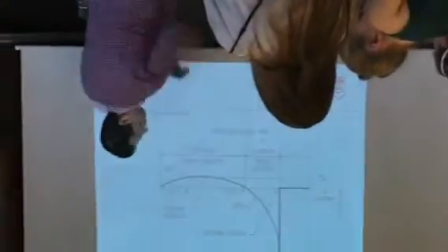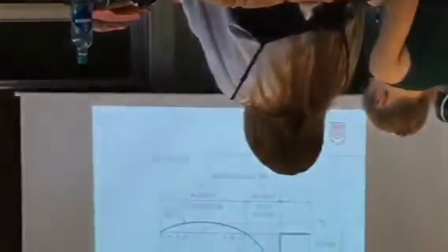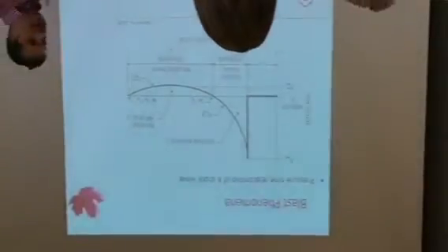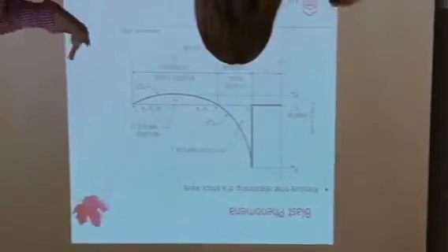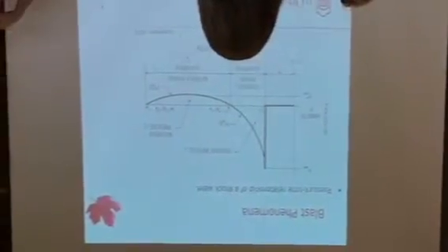So if you've seen blast presented as a triangle, it's for two reasons. One, because this decaying function is being approximated as a linear function. And the second reason is because people ignore what we call the negative phase. The negative phase is this suction that you see. I had a video earlier to show it to you, but I might be able to show it at the end. It just didn't work on its own, so I took it out. So essentially, you see this blast hit the building, and then suddenly it retracts in a negative phase, right?